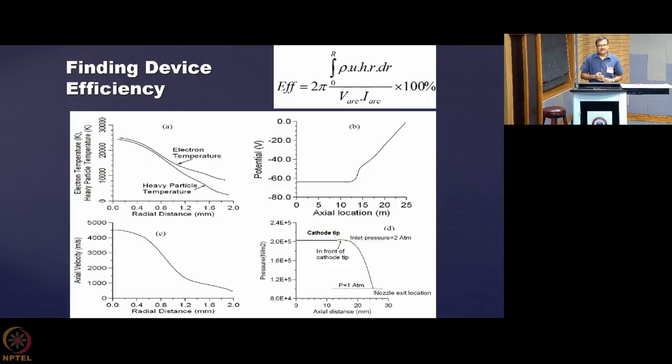Now what is the density over there? Rho. So if you multiply that volume by rho, you are getting what? You are getting the mass in kg. So the amount of mass that is coming out through that elementary cylindrical channel per second is given by 2 pi rho u r dr. So that is the mass that is coming out.